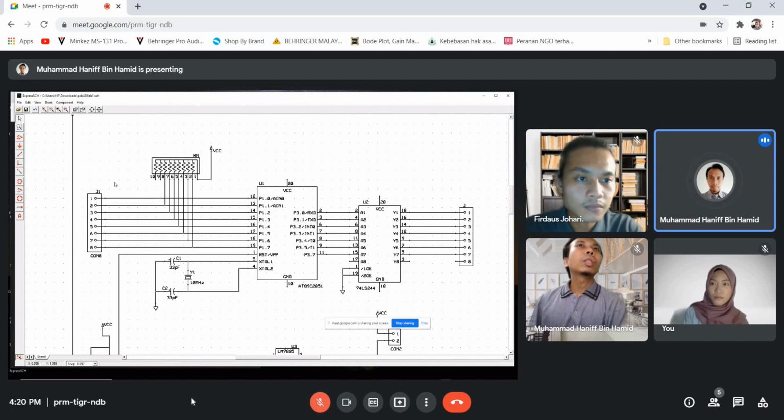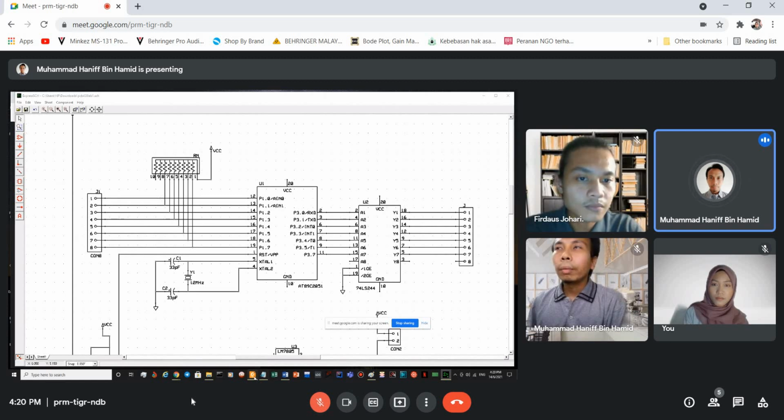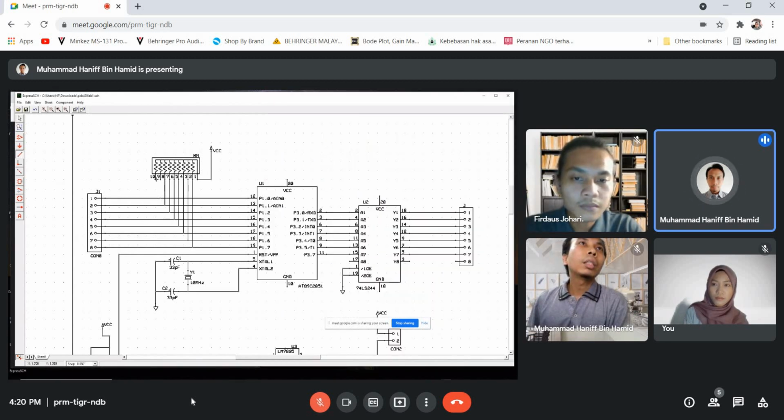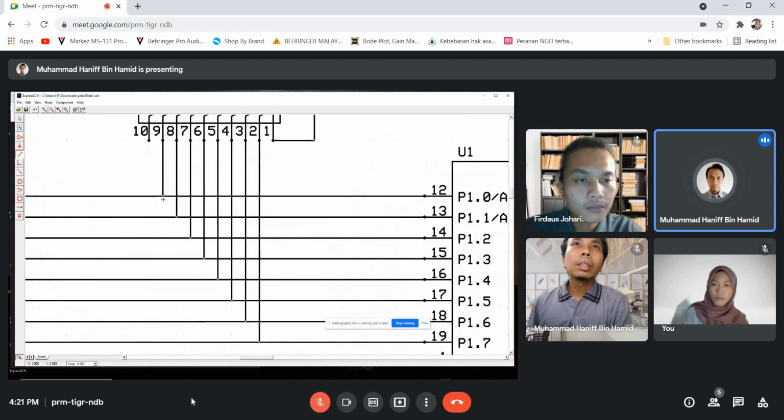To connect the wire like this, from the resistor pin number 9 to be connected with number 1, according to the manual, how you do it is click the wire symbol, place a wire like this here, and click here, connect to number 1, until you can see here it's already connected.